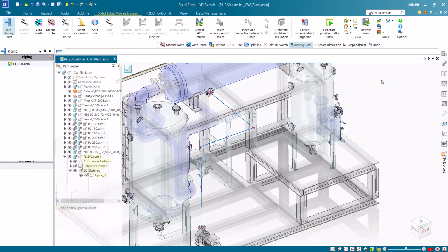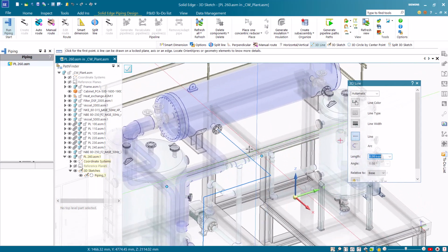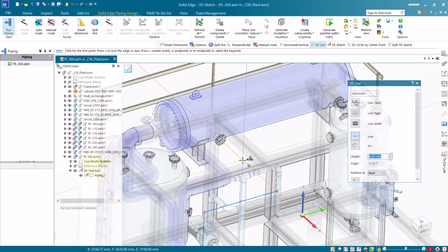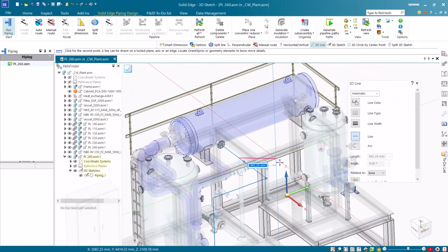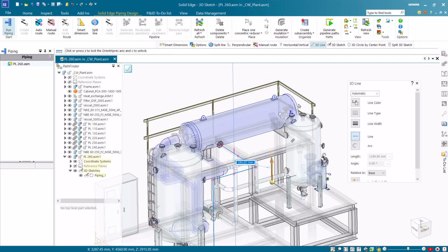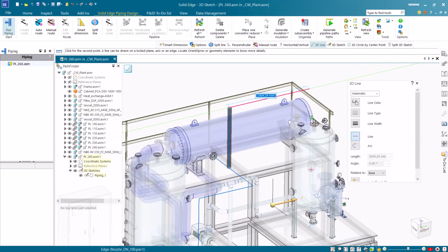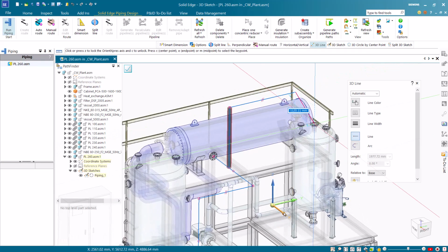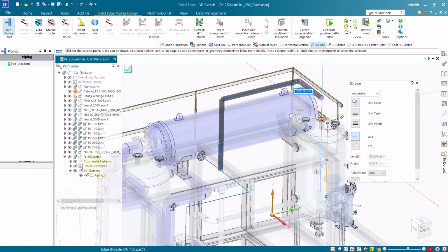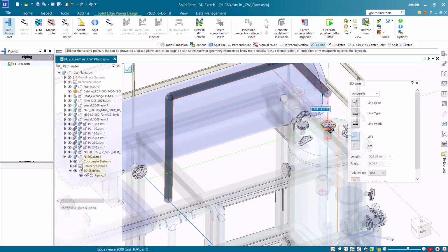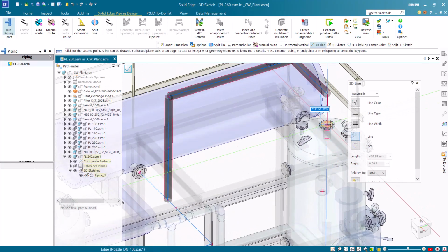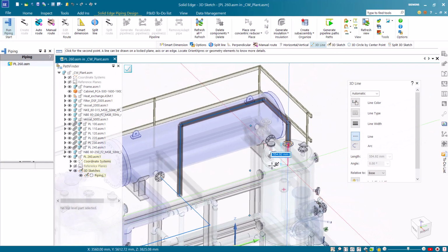The solution also shows different alternative options based on the selection, and we can choose a right option before completing the sketch. Similarly, we can add a branch line and connect to a vessel and define the constraint as required. We can provide geometrical and dimensional constraints. Based on the branch point definition, the piping assembly will get updated later.